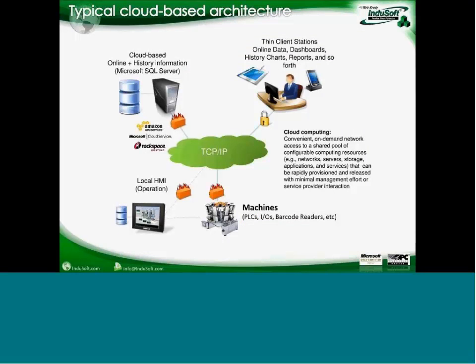And this architecture is also becoming more mainstream, where you typically have a local HMI collecting data from the machine, exchanging data with the local PLC, with the local IOs, and even storing some data locally. And in each machine or each line, you have this local HMI, but you also have a central server at the plant or even on the cloud, receiving information from all the machines, from all the lines.